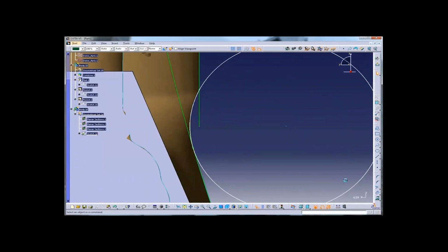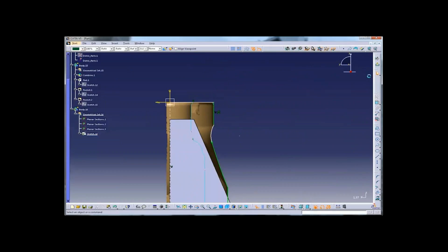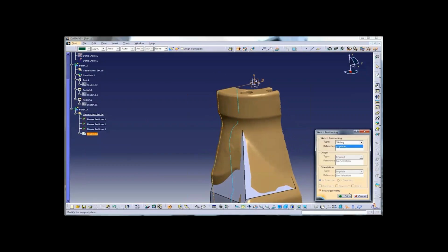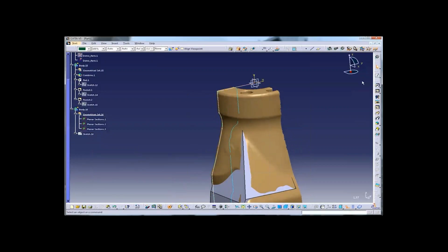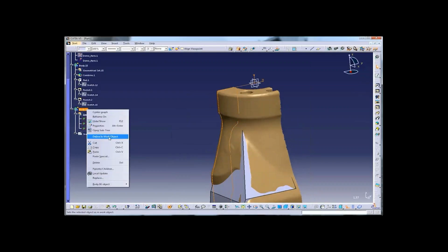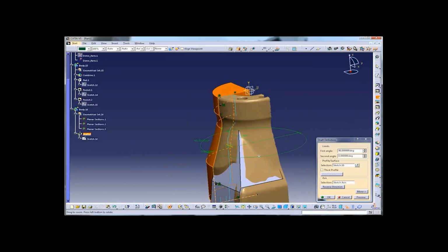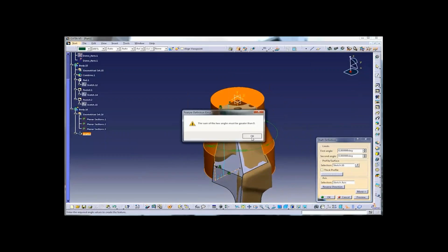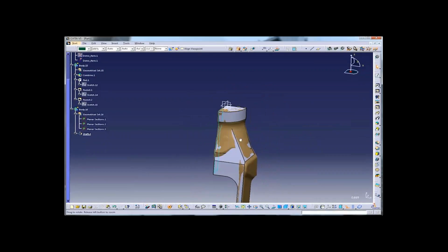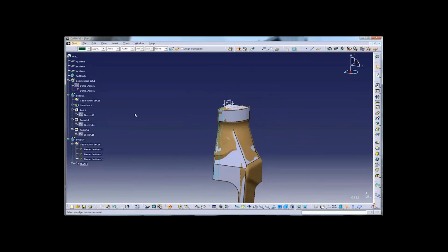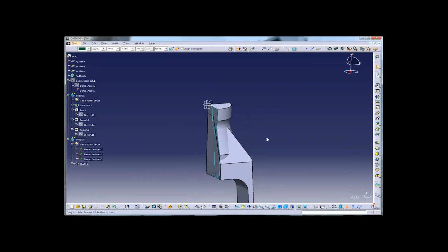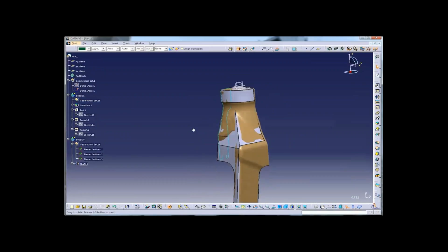I'm going to add more features here. So here an arc, trim them to get a continuous profile. There it is. A few details here, really quick. And then I create my shaft feature over the same quarter of the part we have. So now we have two bodies, and we're going to keep that for more operations at the end.